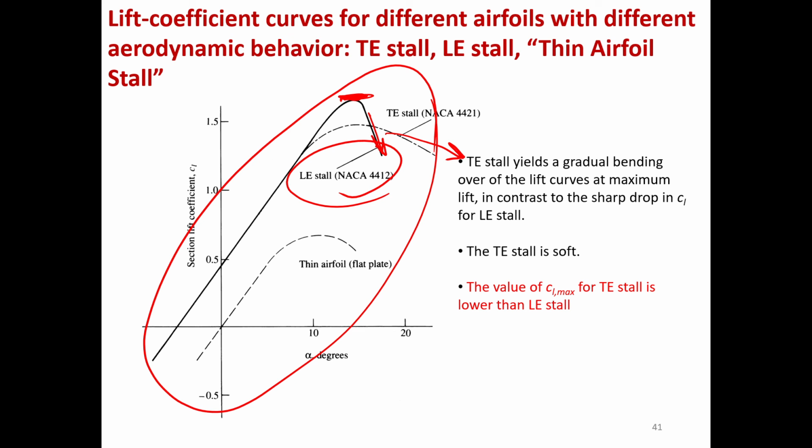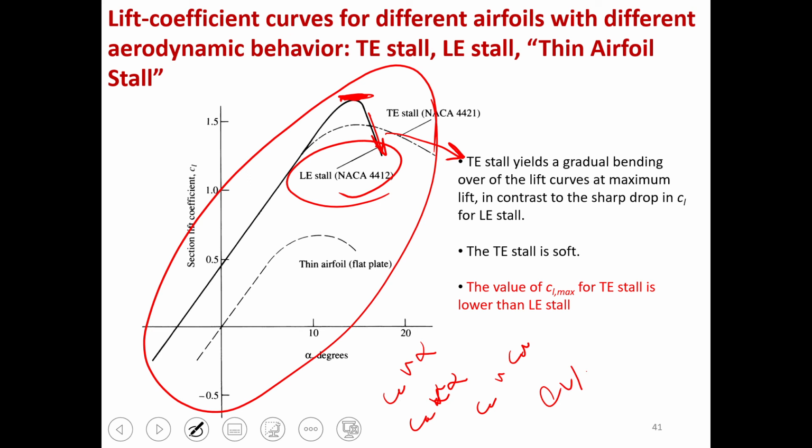So essentially in your lab reports, these are the type of things that I want to get from you. I want to have CL versus alpha, CD versus alpha, the drag polar, CL versus CD, and also the lift to drag ratio versus angle of attack. And we're going to teach you how to fly the airplane essentially, and how to monitor the data, how to get an output of the data, and you should essentially be able to perform the lab without any problems.